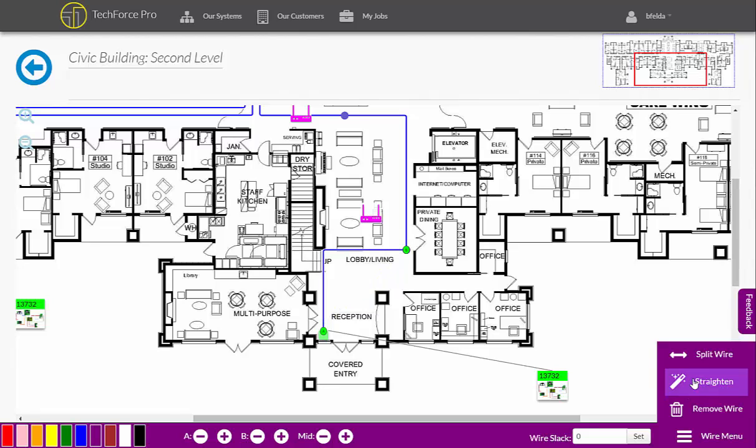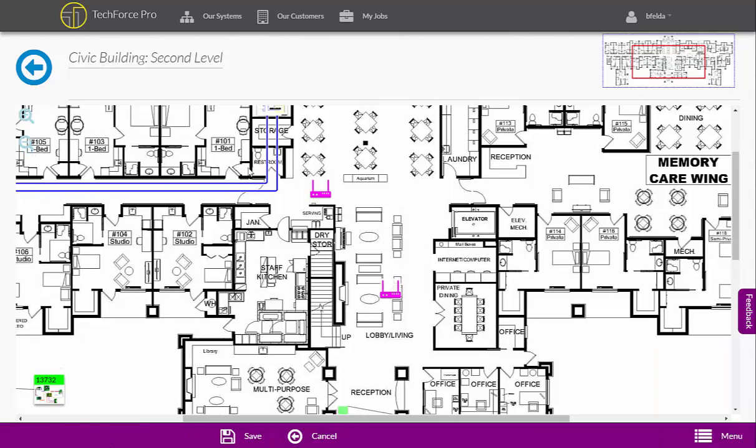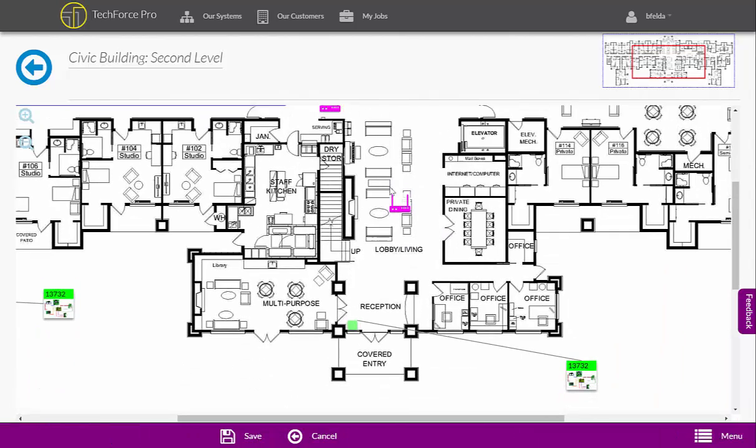Clicking the word flowchart turns it back into kind of like a flowchart wire where it doesn't cut straight, it goes up and to the right, or follows that X and Y kind of axis. Now you saw here under wire menu there's also remove wire, so this is where I can delete the wire. When you remove a wire, it deletes the wire and it deletes all the other ones with the handle all the way back to where the other end connected.